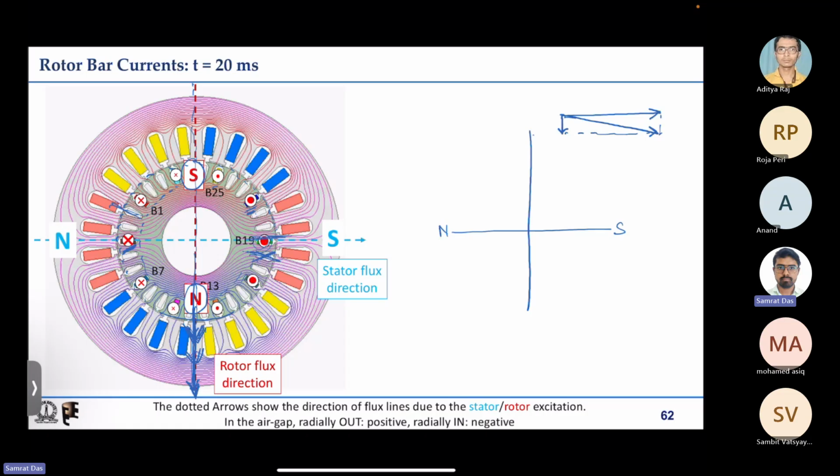But nowhere in any calculation do we take the resultant flux density, because if we look at our individual conductors with a complete turn, in the case of a DC machine, if we calculate the flux linkage either with the stator field only or the resultant field, it will come out the same, because on one side whatever addition it has, the other side has the same subtraction.